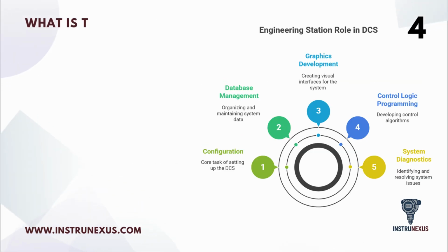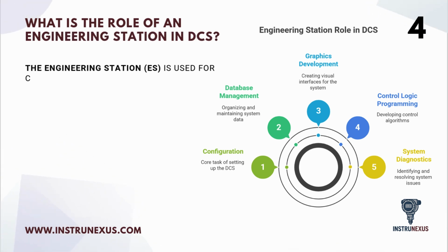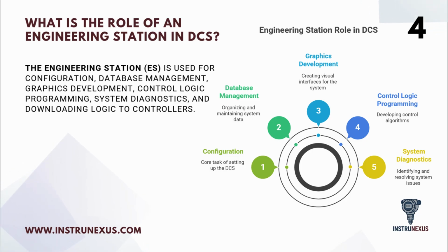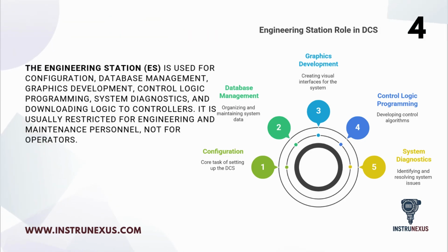What is the role of an engineering station in DCS? The engineering station, ES, is used for configuration, database management, graphics development, control logic programming, system diagnostics, and downloading logic to controllers. It is usually restricted for engineering and maintenance personnel, not for operators.